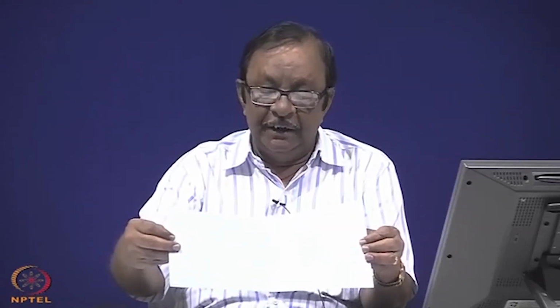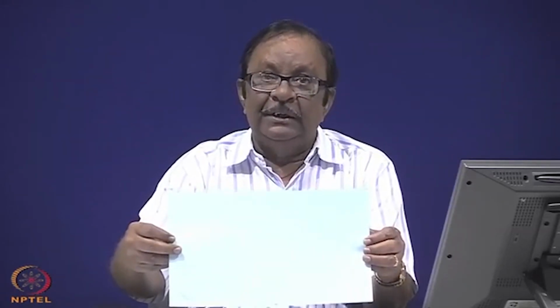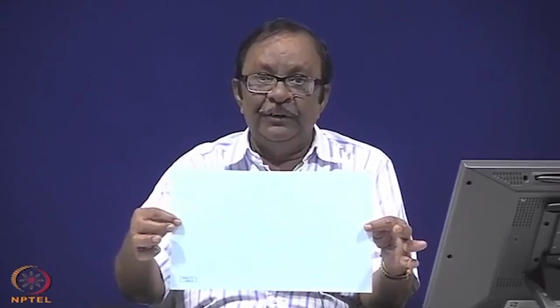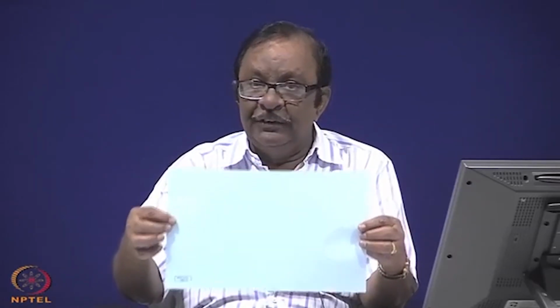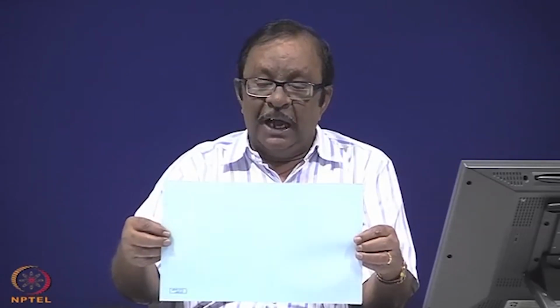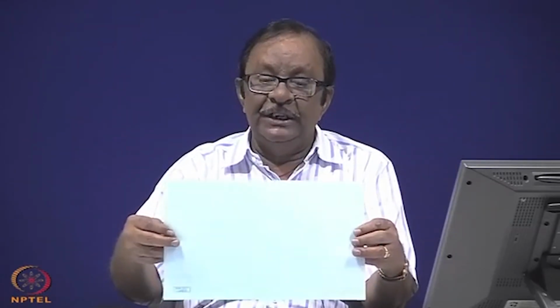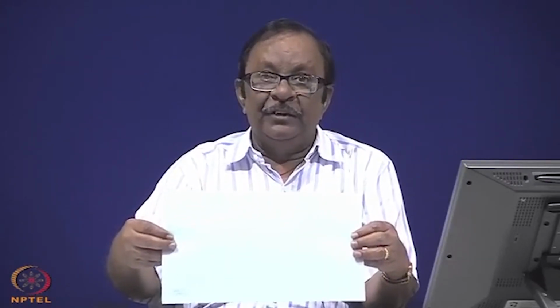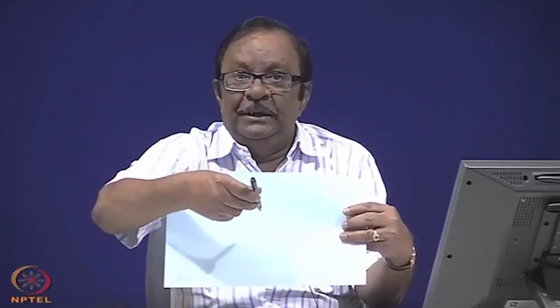So, I may have a lower slope. Okay. So, it becomes nearing the horizontal in summer and nearly vertical in winter, depending upon, of course, the latitude. So, the idea is this is the aperture plane, to my left is the east, to my right is the west, and then I will tilt it like this, change the slope of this plane such that the sun's rays are normal to the plane at solar noon, something like this.